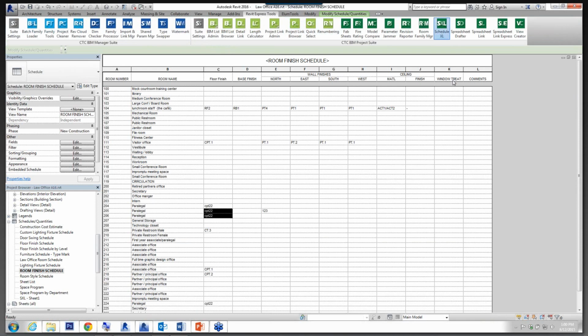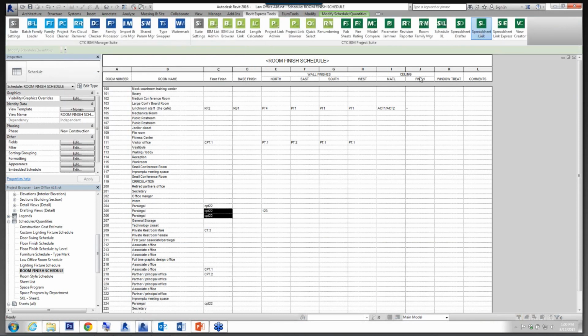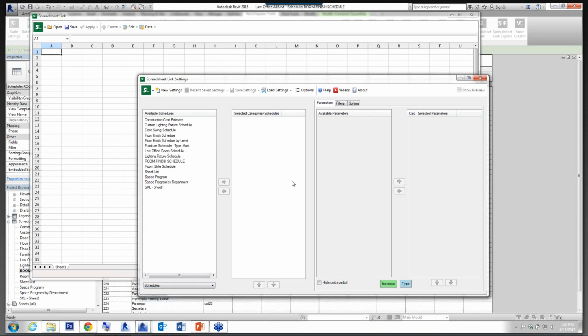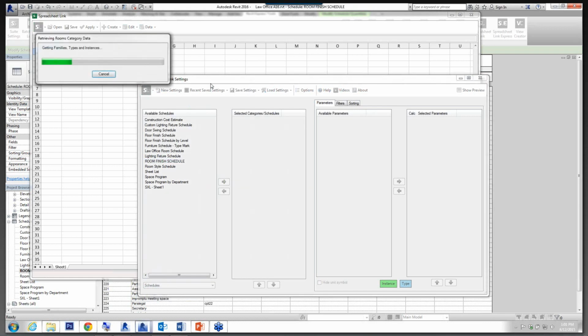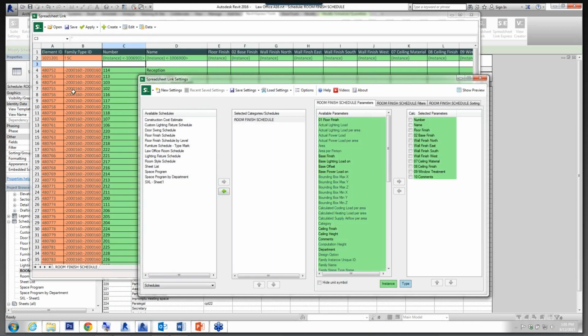You can actually save this to an exported Excel file, and somebody who doesn't even have Revit can edit the schedule, and then that information can be pulled back in later. The trick is that you can't edit the first 2 rows or the first 2 columns, because that's the element ID number and specific info.